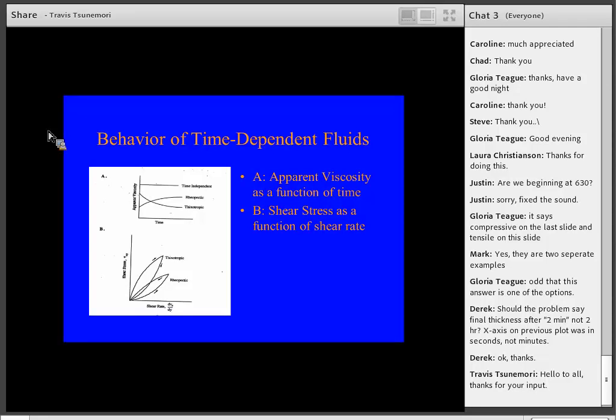As it's moving, it flows. But if you are captured in an avalanche, it's a terrible thing. Just like if you're captured in concrete, it gets thick and heavy and hard very quickly if you cannot apply a strong shear stress. And again, down at the bottom, we've got a sort of standard curve, shear stress versus shear rate. Neither one of these is going to be linear, and they also have different hysteresis type curves as they go up or go down.